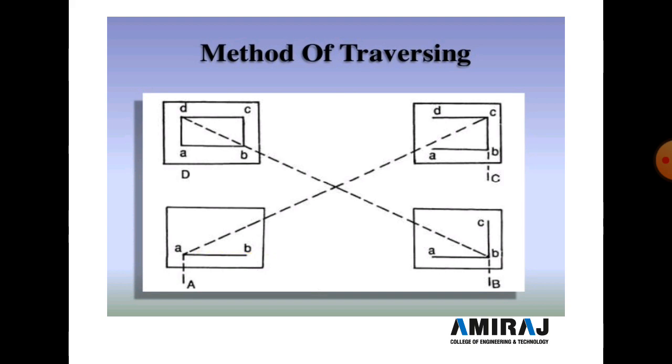We also measure the distance between capital A and capital B on the ground, and we take a scale of 1:1, which means 1 meter is equal to 1 centimeter. Like if the A to B distance is 30 meter. Clear? So 30 meter is converted as per the scale, 30 meter marked as 30 centimeter. So the small ab line is 30 centimeter. Now